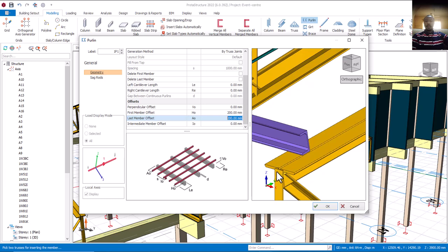You still expect it to go a little bit away from this, in order to prevent water, rainfall. That's fine. So you can now imagine that extension of a roofing sheet, which now makes the roofing sheet exposed to wind. Automatically the wind will start taking this particular place because of the extension. Is that okay?